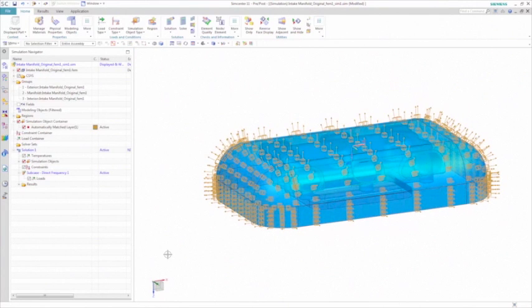The AML is similar to a perfectly matched layer, or PML, that is used for acoustic simulation. However, you don't need to physically model the AML unlike you do for a PML used in other tools. This means the AML, which is only available in Simcenter 3D, reduces both your modeling time and even solving time, since the FE acoustics models are smaller.